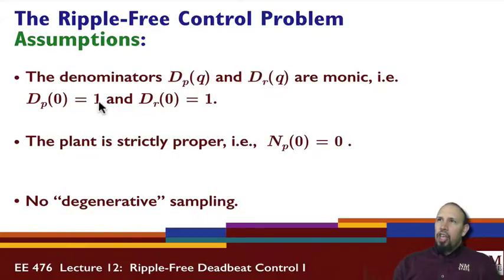So the main thing here is that q itself is not a factor, or there is no root at 0 for either of these two polynomials. That's one of the key assumptions in all of this. It turns out that if you did have that, you can actually redefine the transfer function in a way that we will not get 0, or else you'll have a system that's not causal. So part of what this implies is that our system is actually causal, and that's again a very reasonable assumption. Also for our reference input, it's a very reasonable assumption that we have a causal input and a causal system. So causality is a very reasonable assumption.